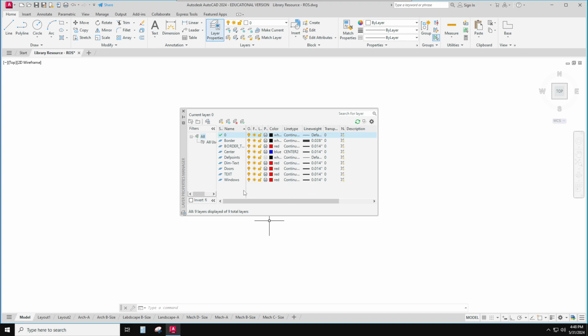But now I need to make a new one, and it's going to be geometry. So I'll go up to the little tiny, it's right above the list of names, and over to the left, and it's got a little yellow star on it. New layer. You can also type Alt-N. New layer, and there it came out, and I got to give it a name.